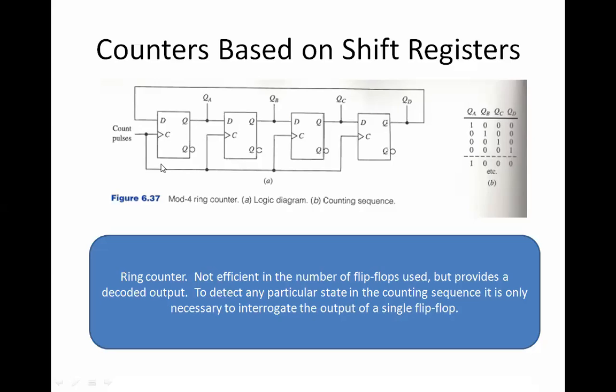Understanding now what I'm trying to say? Q bar is not necessary, no, sir. Yeah, that's what I'm trying to say. Most of the times we don't use Q bar at all, right? So most of the modern circuitries do not exclusively build Q bar in their ICs, in their integrated circuits. If you are in the worst case in need of Q bar, then you connect this Q to an inverter, and the output of that is considered as Q bar. Okay, so that's the concept.